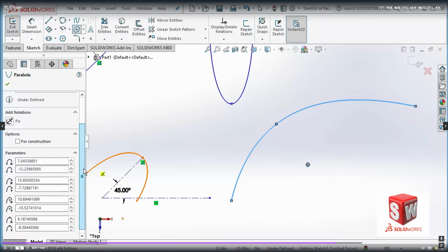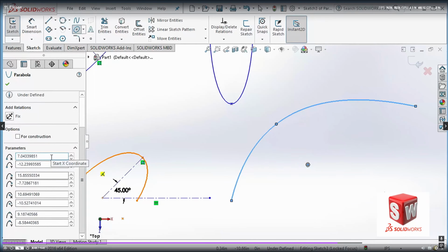So what are the properties for that? You can see that there's a start coordination again. There's an end coordination here. There is a center coordination, and of course there's a midpoint that's called apex. Actually, that's apex. I didn't remember that. The name was so complex to me. That was the apex. So we have center, we have apex, we can move all of them. So what I'm going to do is to click on this OK.